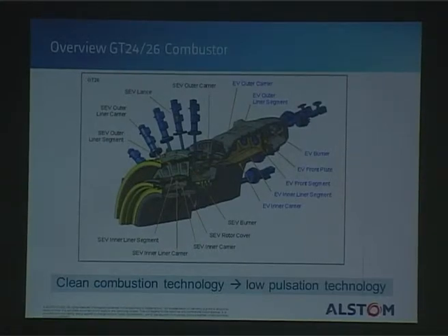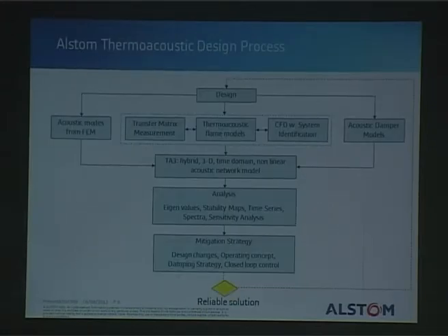And then in practice, what you need to do is some staging, or you have to operate your engines at conditions where you would normally not do that. And that is typically where you get higher NOx emissions again. So really, to achieve low NOx emissions, you need to get the thermoacoustic pulsations under control. I need to be able to predict them at a very early design stage in order to really do something about the problem. So how do we do that?